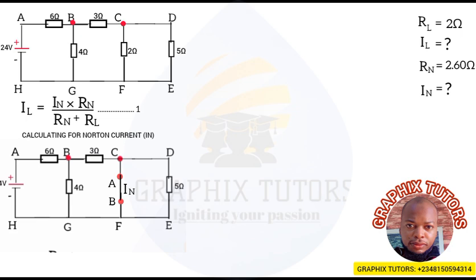Current flows from the lower potential to the higher potential. Let's say the current is I1. I1 keeps flowing through the 6 ohm and gets to what? Node B, where it splits further into I2 and I3. I2 is the one flowing through 4 ohms, but I3 will continue flowing through the 3 ohms until it gets to node C, where what will happen?